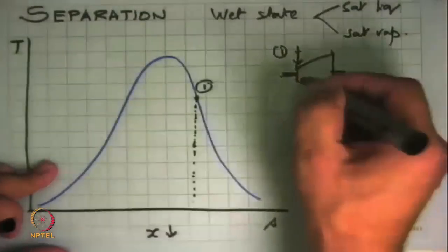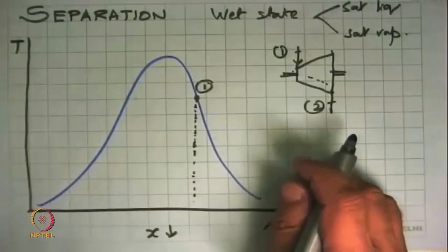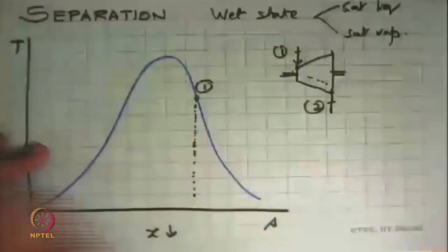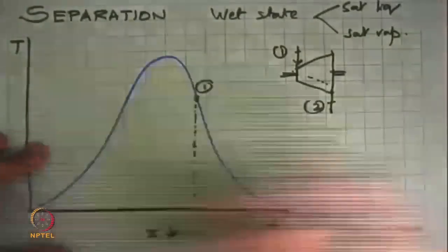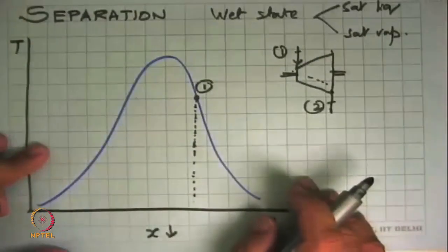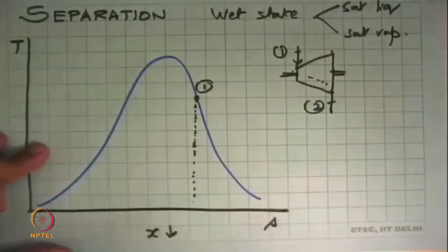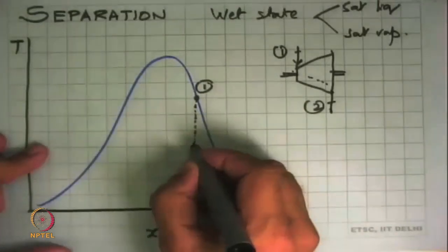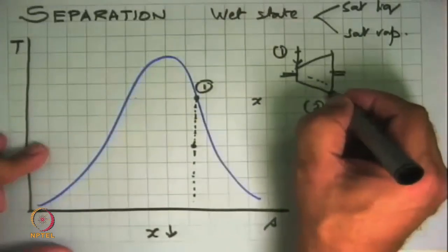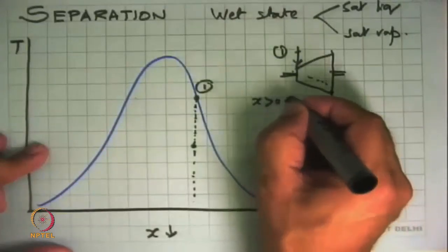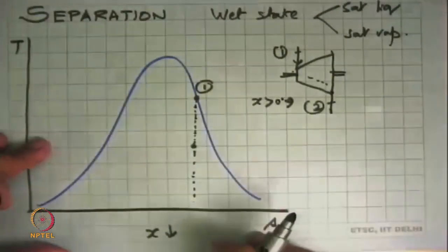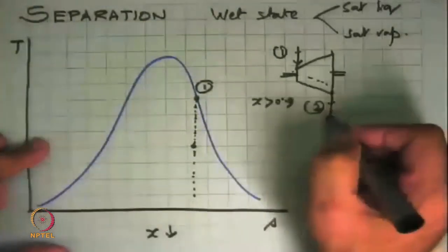Which means that the amount of liquid flowing in a turbine is increasing, and this is largely dispersed as very small drops, and they can go and hit the blades. They don't follow the same expansion law that vapors follow, so the design and engineering of this type of machine becomes practically impossible. So what one does is say, okay, I can make a machine with exit dryness fraction more than, say, 0.9. So I can design a turbine and it's reliable up to this point. So at 0.9 we take it out.